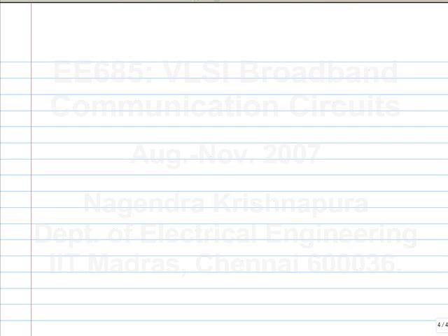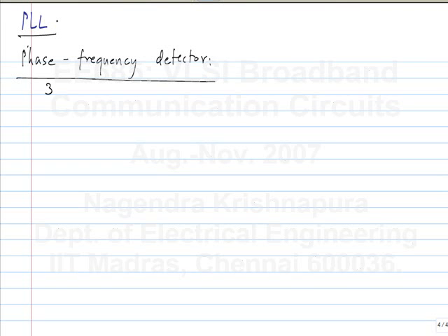So just a quick summary of the PLL. You use basically the phase frequency detector, that is the 3-state detector, which has become the standard. So, we will assume that that's what we will use. We will typically not use XOR gates and so on. So, that is mostly for playing around. You don't use it in practical systems. Okay. So, this is a 3-state state machine.